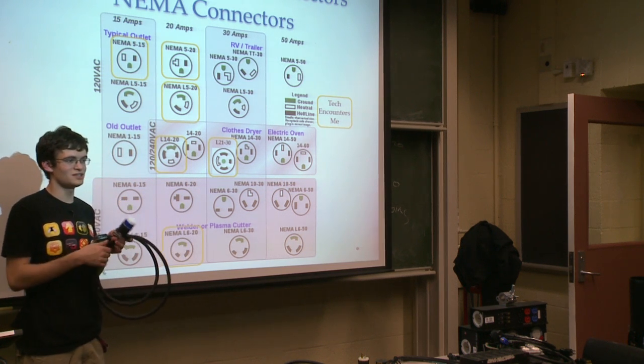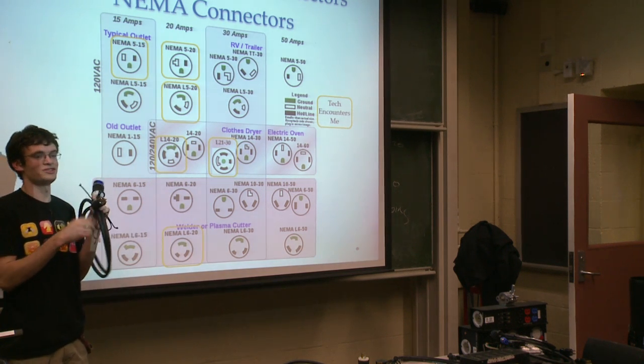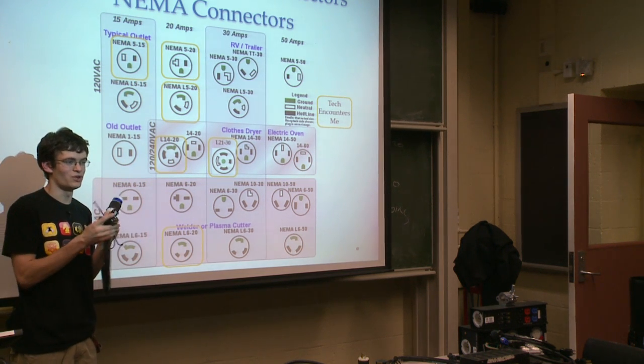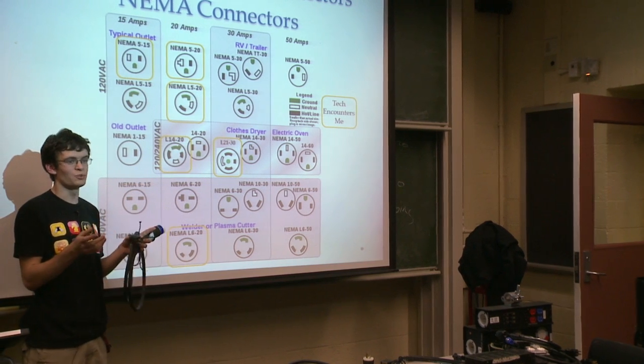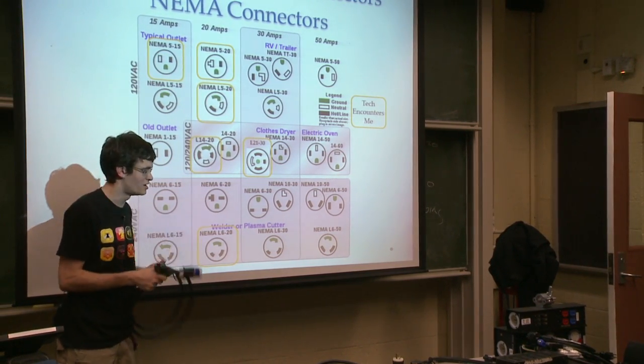However, some instruments that have an L6 connector, such as a VL3500, only want 208 to 250 volt and will not be happy with 120 volt and will refuse to turn on. You probably won't break them. They'll just not turn on.